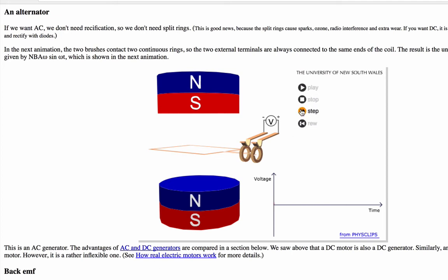Now we're going to step it through, and I hope you thought that the voltage should be initially 0, and that now, as the area of the coil that has flux lines through it is decreasing, we have an increasing voltage, and we will get to the point where the loop is vertical. At this point, the actual flux through the loop is 0 because those field lines are running parallel to the loop. But the rate of change of flux is a maximum.